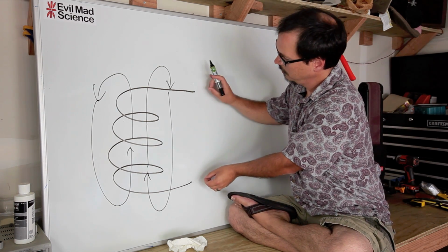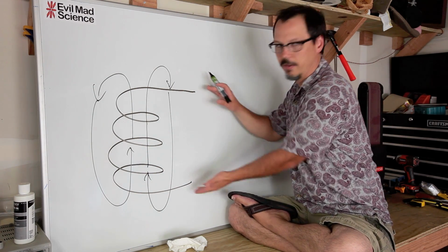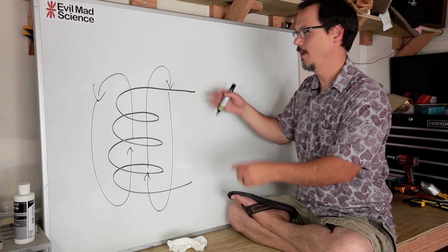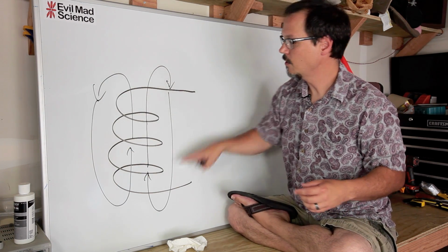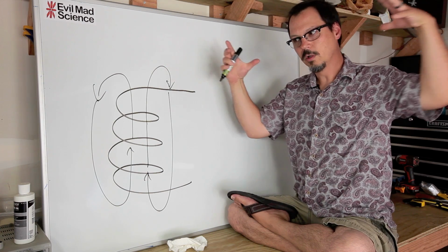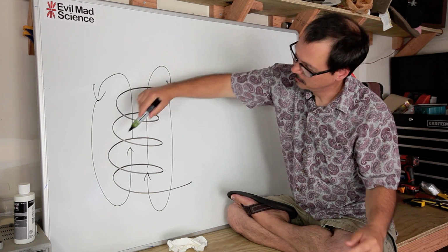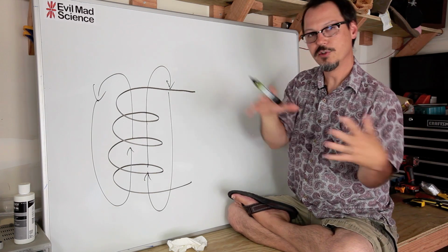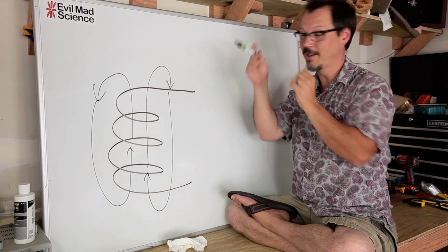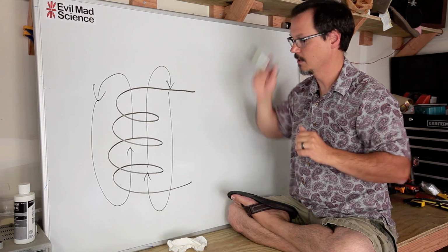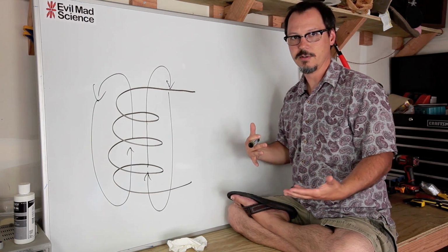Because once you take away the motive force, like if I had a battery on, and I took the battery off, all the energy that's stored in this magnetic field will collapse down, and as it does so, it cuts across the wire and induces that current to keep going. I got an example that I'll show you later on at the end of this, I hope. It stores energy in the form of the magnetic field, and it resists a current change, okay?